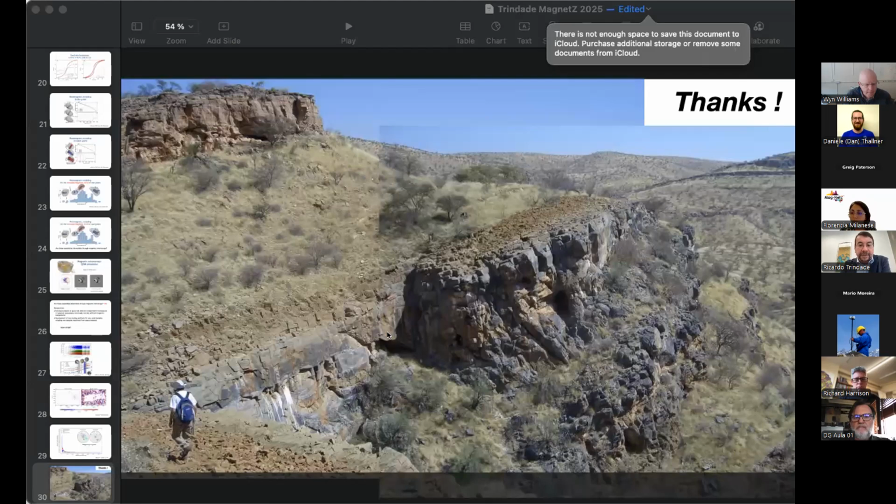It's the spatial resolution. It's completely different. For CT scan, you can go down to usually 1 micron, whereas for ptychography, you can go down to a voxel size of some tens of nanometers. So there's a big difference between CT microscan and ptychography.